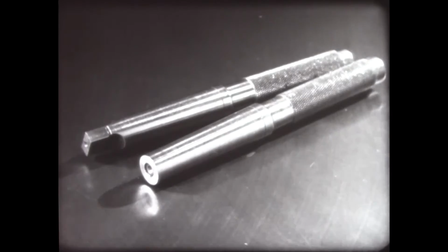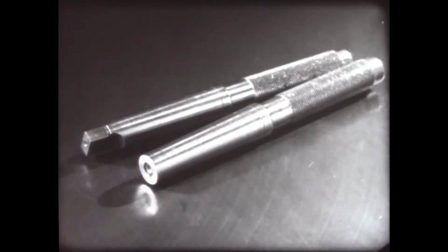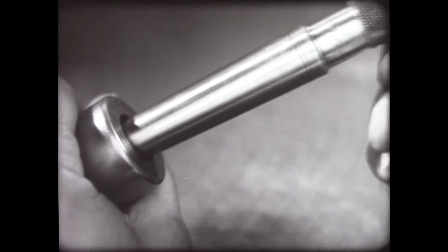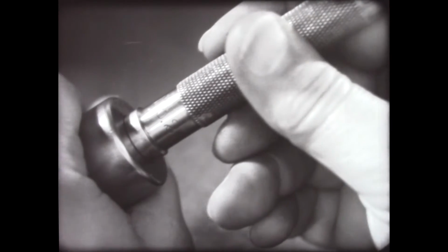Taper plug gauges are made in many sizes and with various angles of taper. They are used to gauge both the sizes and the angles of tapered holes. This is a number 2 Morse taper plug gauge. The limit mark is in the form of a fine groove encircling the gauge. This gauge checks both the angle of the taper and the size of the hole.